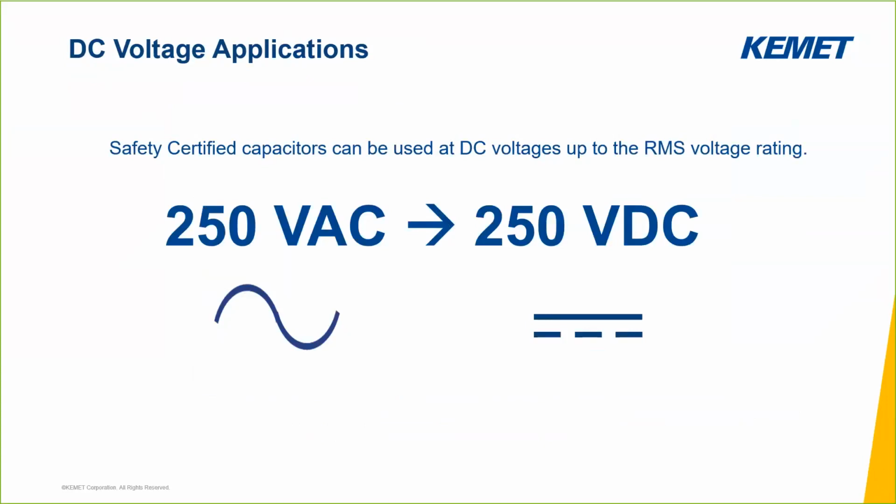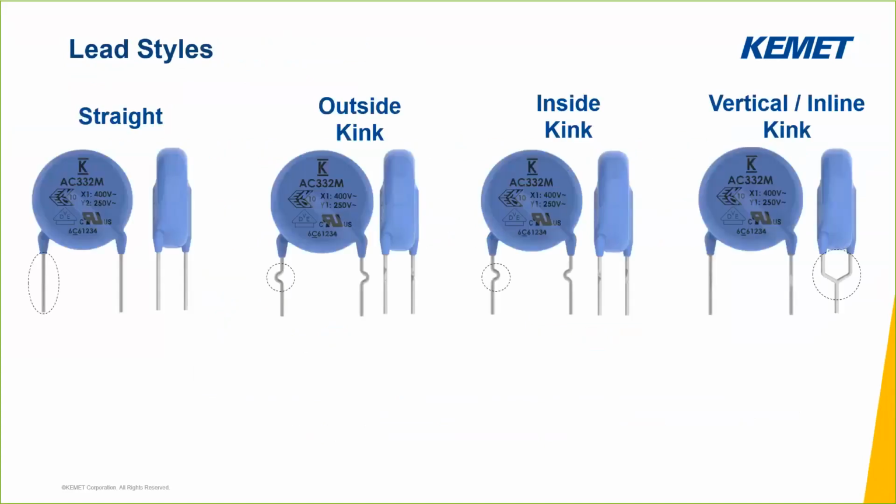Now, historically, all ceramic safety capacitors were in a leaded disc form factor. It's common for leaded disc safety capacitors to come in multiple lead style configurations, and the most common are straight, outside kink, inside kink, and vertical kink, which is also called inline kink. Each of these lead styles is a modification to the lead form and not to the actual disc itself.